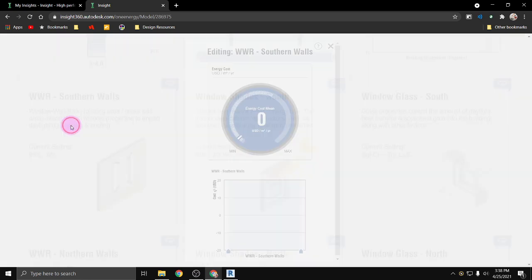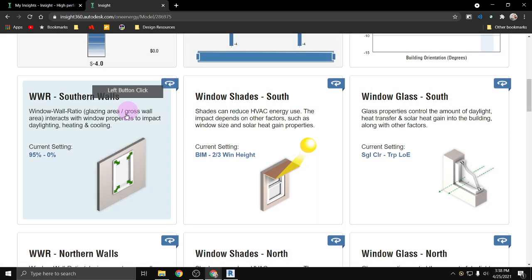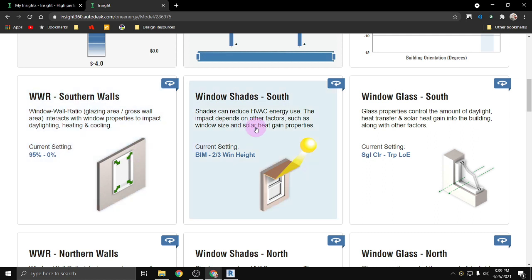And then I can also look at my windows, like what type of windows do I have set up? So that's your window wall ratio, which parts of my walls are glazed glass versus the actual wall itself. You'll notice in my building that most of it is. And for me personally, and probably the Eames would agree, the fact that this building is all curtain walls and all of those glazed windows is kind of the point. So I maybe don't want to change this too much.